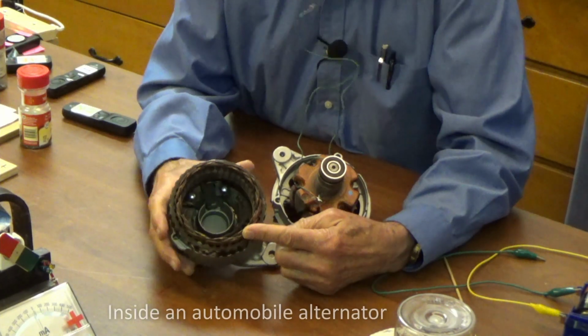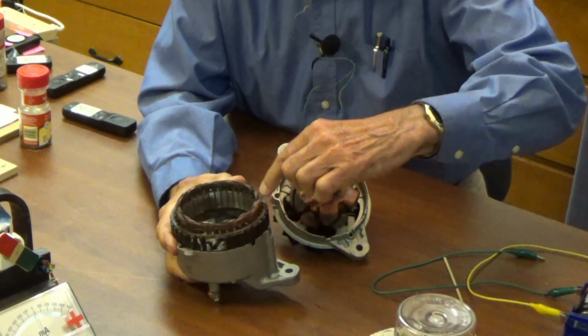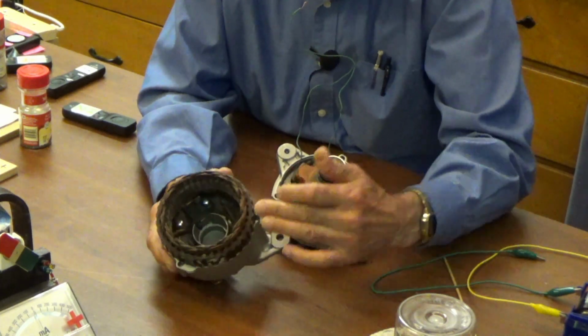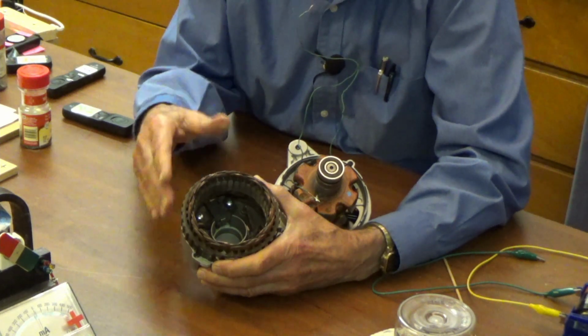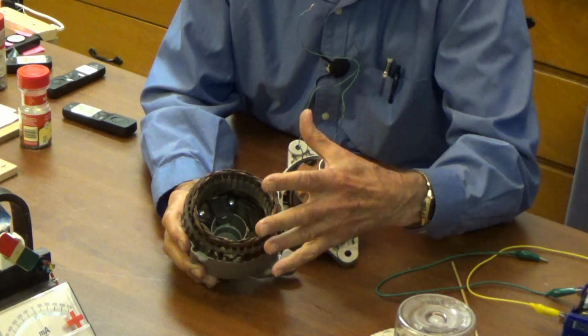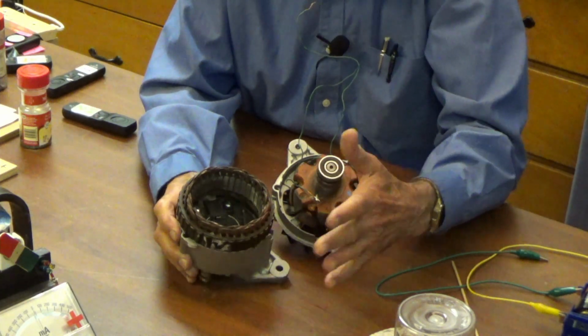So this part is stationary, and it's got windings embedded in a slotted core of steel. It's laminated. Remember, whenever we have rapidly changing magnetic fields, we want the core to be laminated so it doesn't waste a lot of energy creating electrical currents in the core. That's all useless energy.